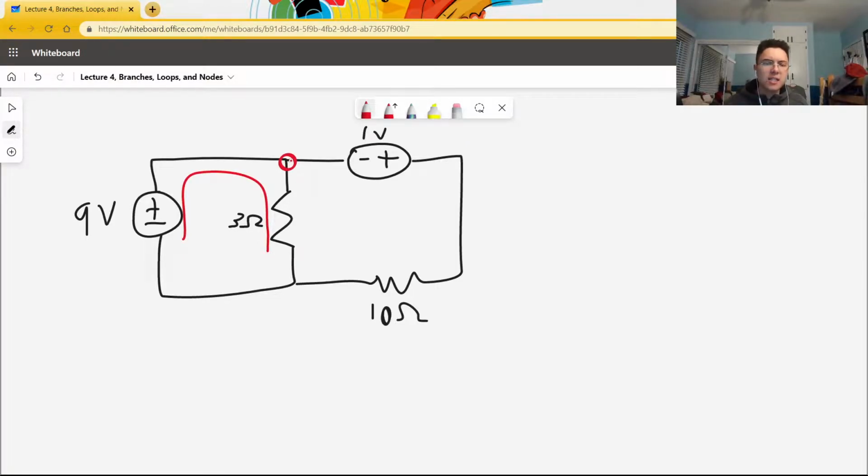That is because at this point on the circuit, you can go one of two ways, either to this resistor or to this battery. If, when traveling across a circuit, you reach a point where you can go in one of two or more different directions, the branch you are on has ended. So, this battery and this resistor are on the same branch because you can travel from the battery to the resistor without facing a point where you can split in two different directions.